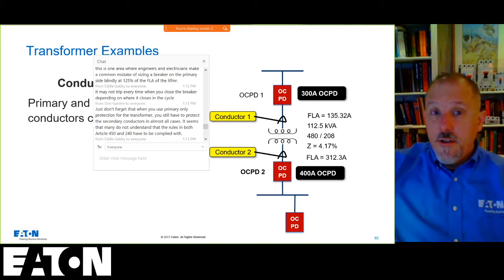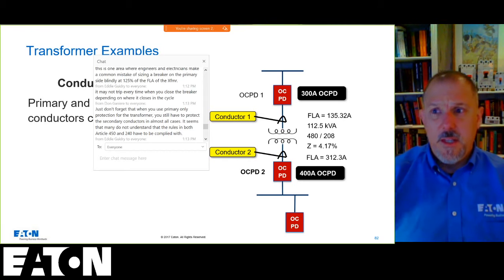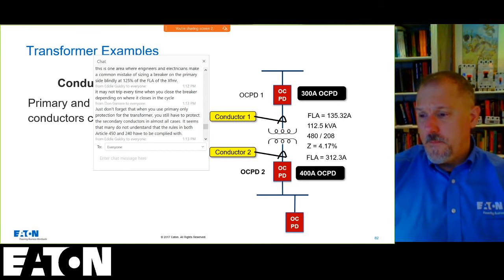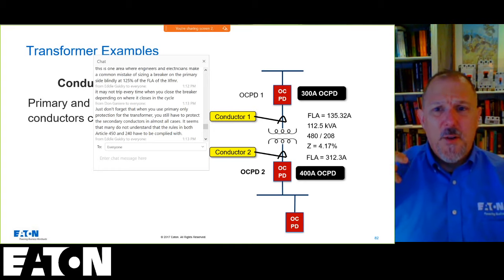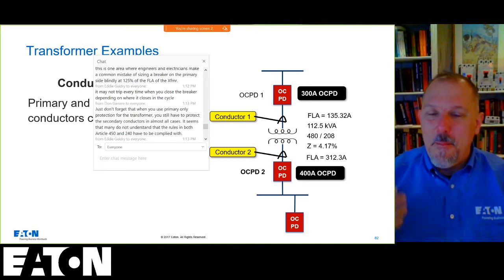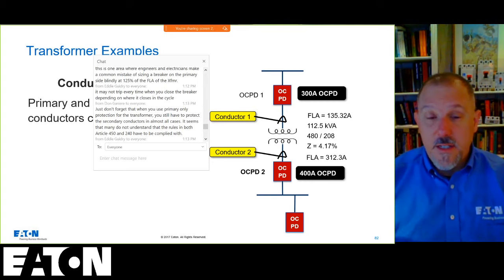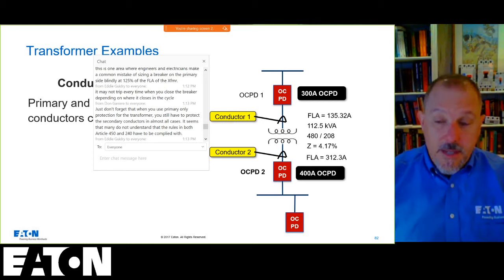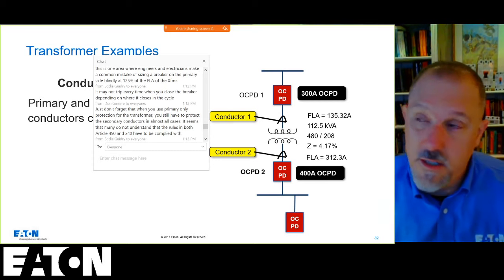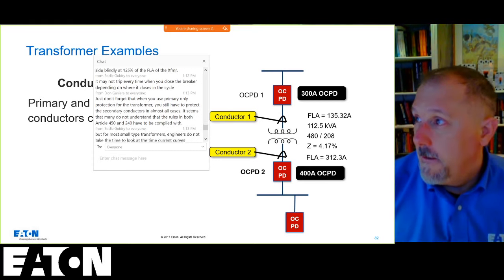You look at large transformers, we put differential protection, we put temperature sensors in there, we put oil monitoring, we do a lot on large equipment because you spent a lot of money on that piece of equipment. You will do a lot of things on larger equipment that you won't do on this little dry type. Number one, because technically you can't, but in other cases you wouldn't, because it's just not worth the cost.